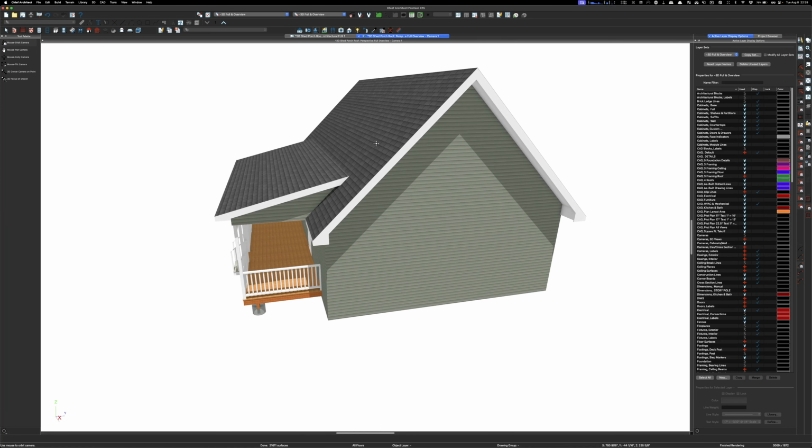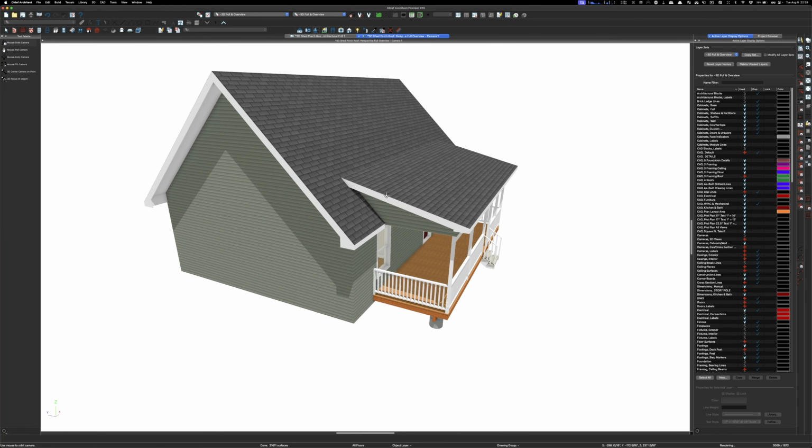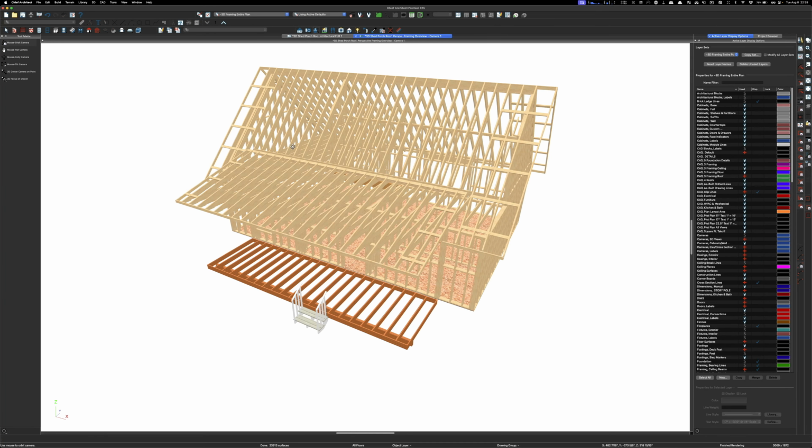I don't think trusses work really well here. I've seen it done where you could truss this roof and then this would become a lay-on. You would put sheathing and plywood on here and then just lay this on. But traditional framing would be rafters, and then these rafters would go through and tie together. So I want to show you what Chief does.